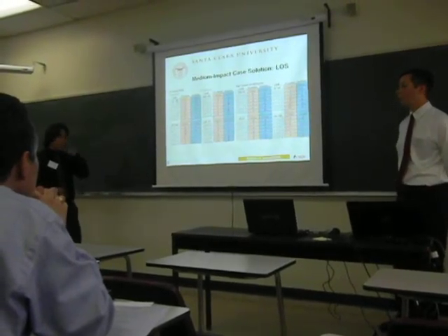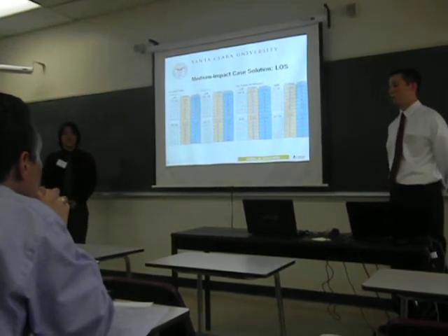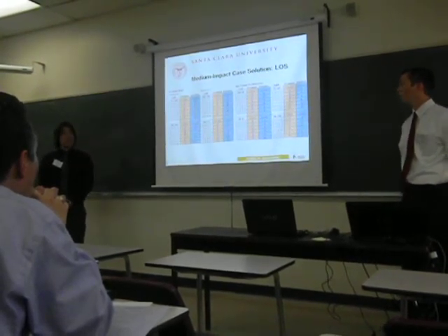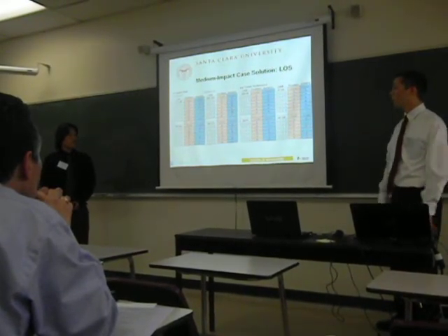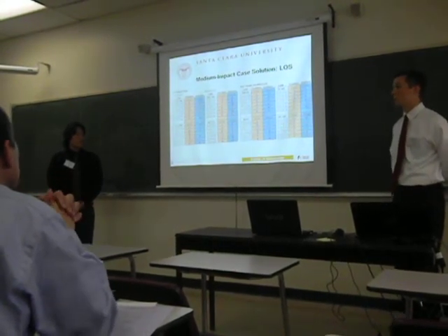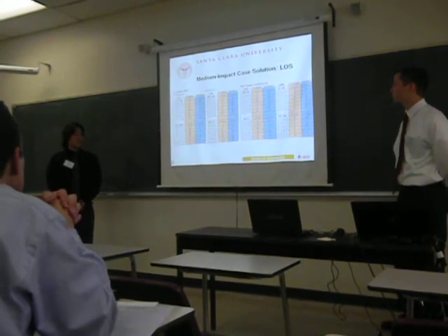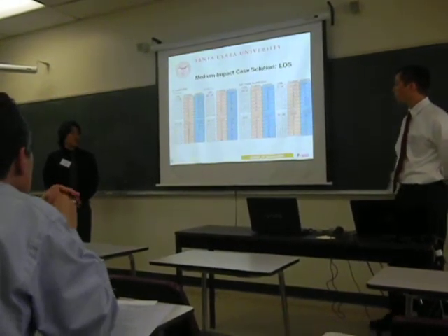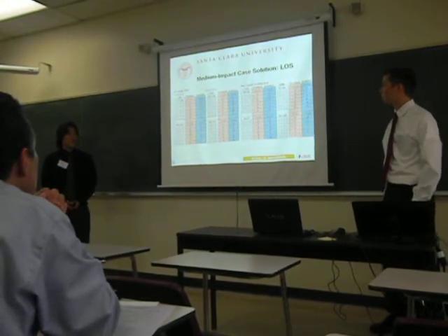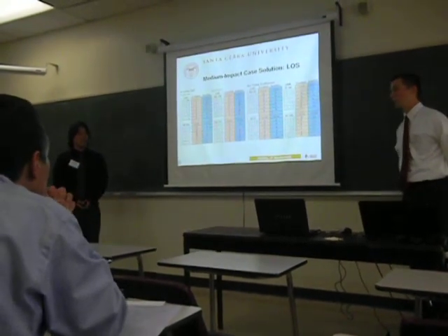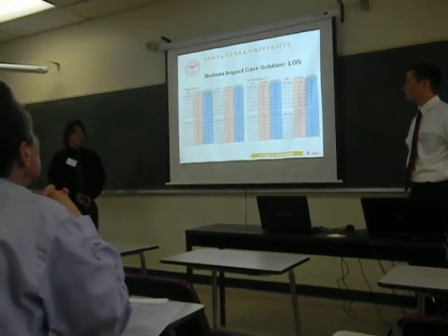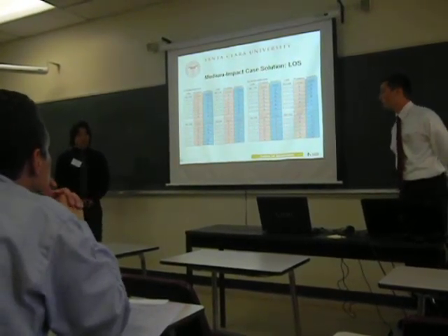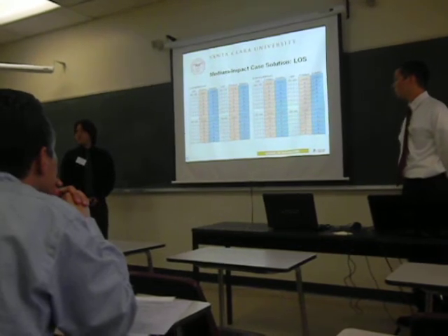We also reran the LOS test for all the corridors we analyzed in the problem scenario. And the solution, which is marked in the blue columns, overall we saw a general improvement in LOS for all the corridors, especially here surrounding the intersection at Santa Clara and El Camino Real. Similarly for Scott, north and southbound, we saw general improvements.